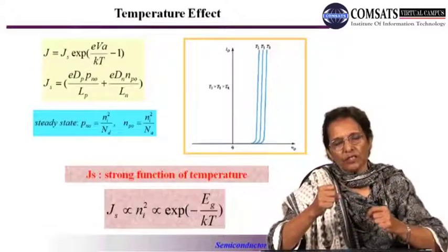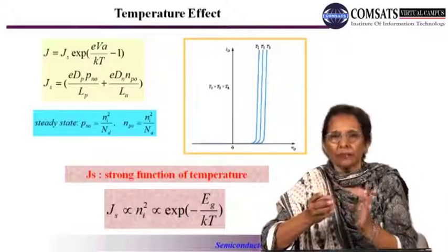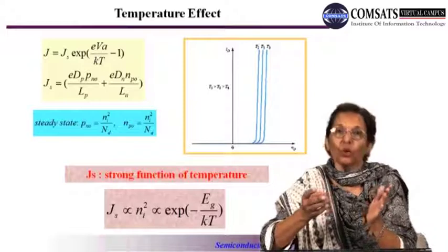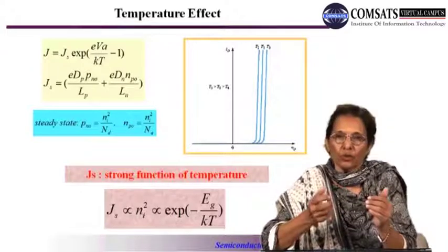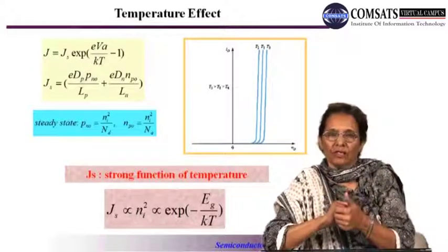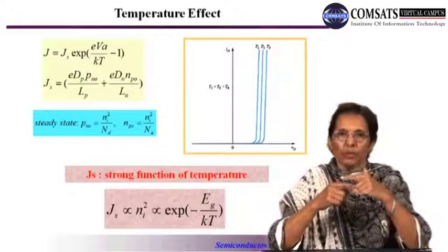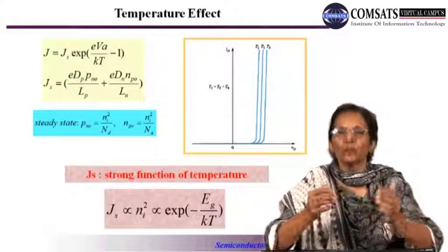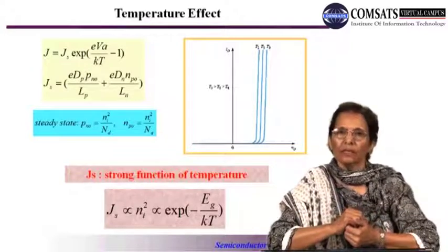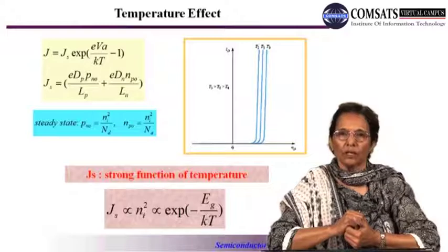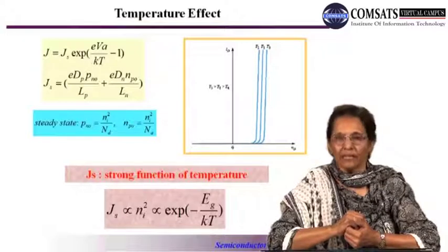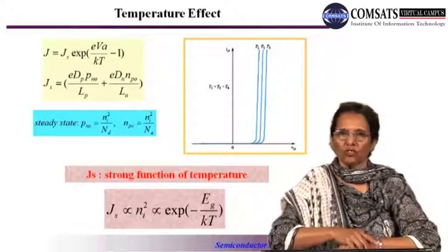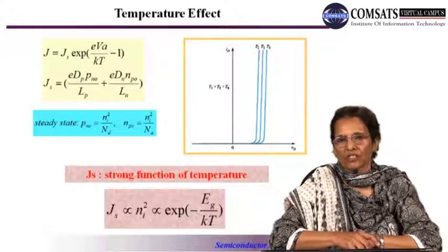As the temperature is increased, what follows? The thermal energy that the crystal receives also increases. Electrons, due to this increased thermal energy, will break the bond. That's the simple mechanism of bond breaking, or the simple mechanism of thermal generation of electron hole pairs in a given semiconductor crystal structure. So this was the concept of bonding in the crystal structure.